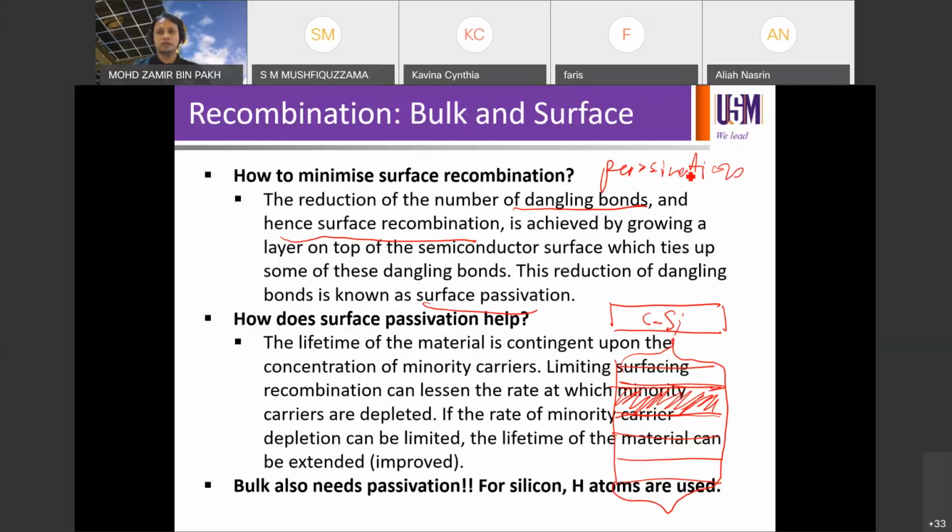So usually for the silicon process, for crystalline silicon, the dangling bonds are not satisfied, there's no complete bonding. So these dangling bonds appear as defects in the lattice. When you talk about defects, they are SRH recombination centers, right? So they need to be fulfilled. You need to have some bonds to have them satisfied.